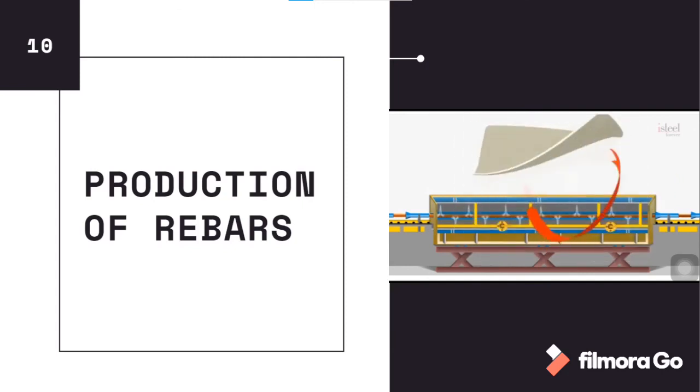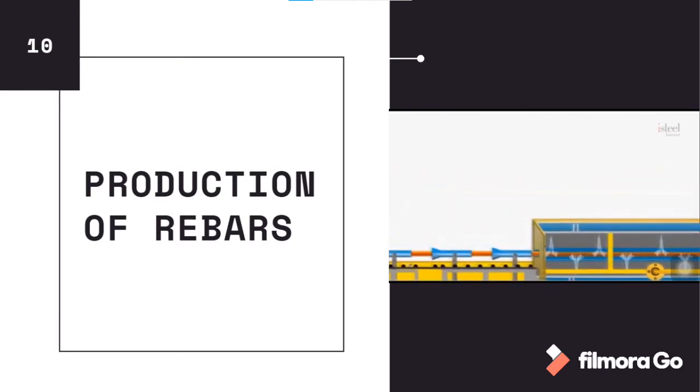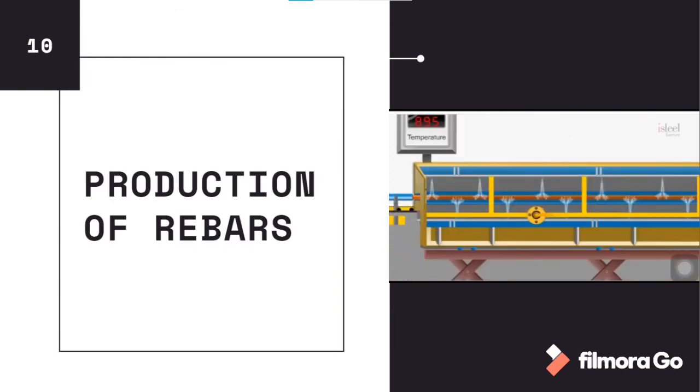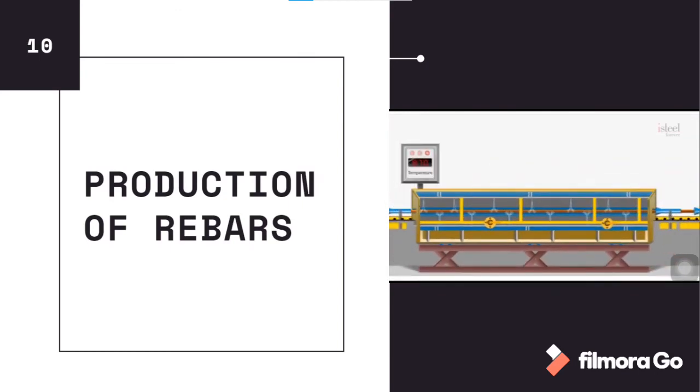iSteel has further improved this process and now has a new water quenching system. Since different parts of the bar entering the cooling chamber vary in temperature, computer-controlled quenching ensures that the amount of water sprayed onto the bar varies depending on the temperature of that portion of the bar. As a result, we have a bar of similar strength across the length, something that few TMT construction bars can